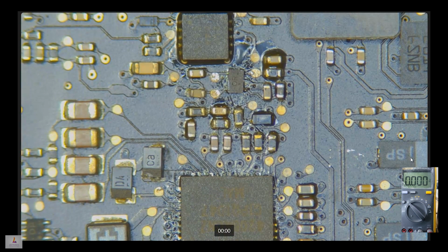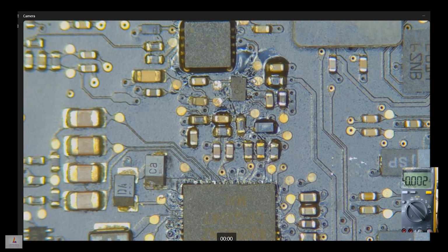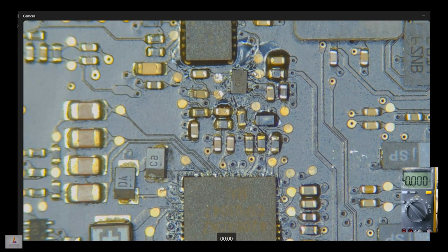All right. And I can't tell if that chip was shorting my output voltage. But if that capacitor was what was shorting my output voltage, it could be, and it could also be that that capacitor had drained too much power out of that regulator and killed it. So I changed that capacitor, and I was now getting my 4.5 volts.